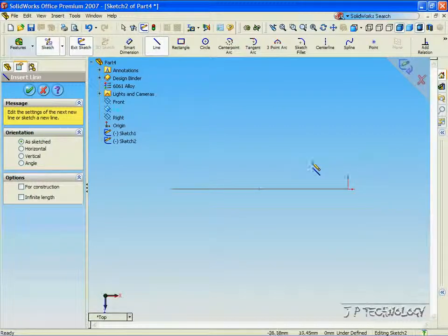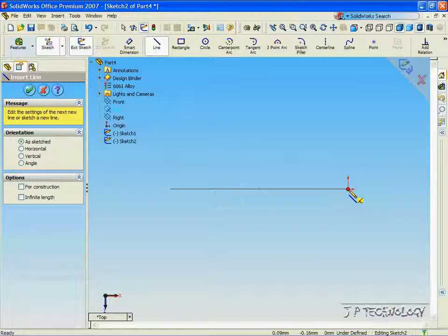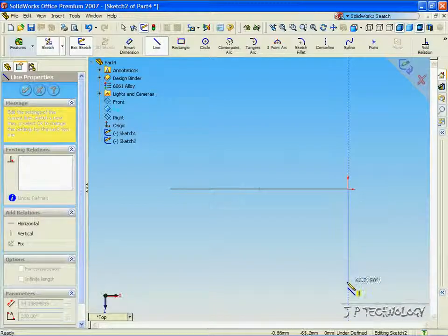Now it's very important to know with the sketch that we're going to be extruding out with, the profile line has to touch somewhere on its outside. So as we made it touch the origin, we're going to make our profile line that it's going to follow right on the origin, and it's going to be touching the edge. So we can bring it out, bring it across.